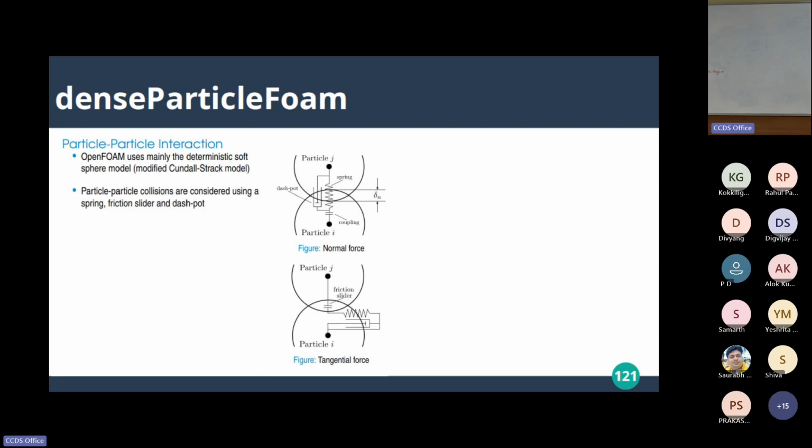When particles are quite close to each other, they have inertia. They can hit each other. They should bounce. They should deform. Maybe they should rotate. They should contribute a certain kind of force and stress distribution. For that, again, certain low dimensional models like spring, dashpot, and mass kind of models they will have. And based on that, how much energy is supposed to be lost, how much reflection happens, one will be in a position to take care of certain contact forces. Hertzian kind of description and other things are there. So these are the modules to take care of the additional impact of these particles.